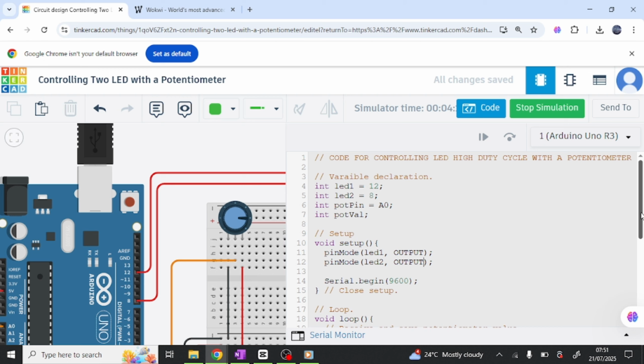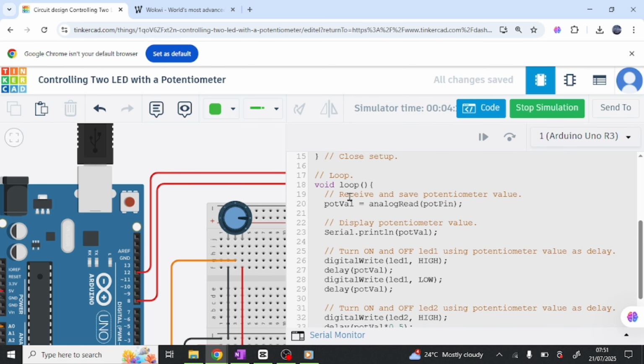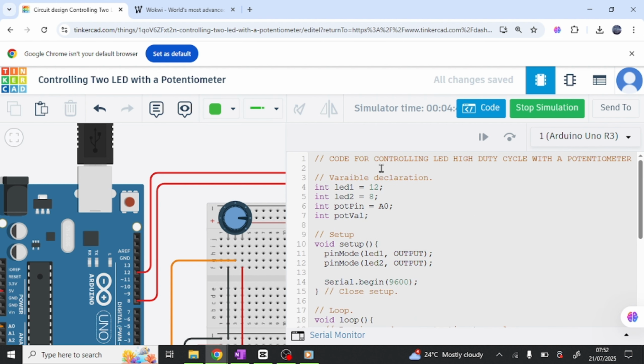So now that happens in the void loop, in the loop function. Where is our digital read, digital write again? Good. Now digital write, meaning this LED, which is pin 13, this digital write is a function that also takes two arguments, the pin number and then the states. So that's pin 12. That's what we said in this code, pin 12, for LED 1.